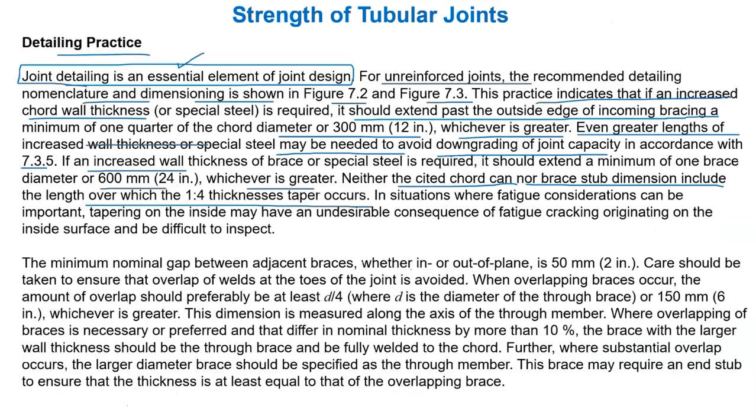In situations where fatigue considerations can be important, tapering on the inside may have an undesirable consequence of fatigue cracking originating on the inside surface and be difficult to inspect. Whenever we have this kind of 1 in 4 transition, if it is inside, in fatigue problems it is difficult to inspect, as maybe some crack is happening inside. So it's preferable to keep the transition outside.